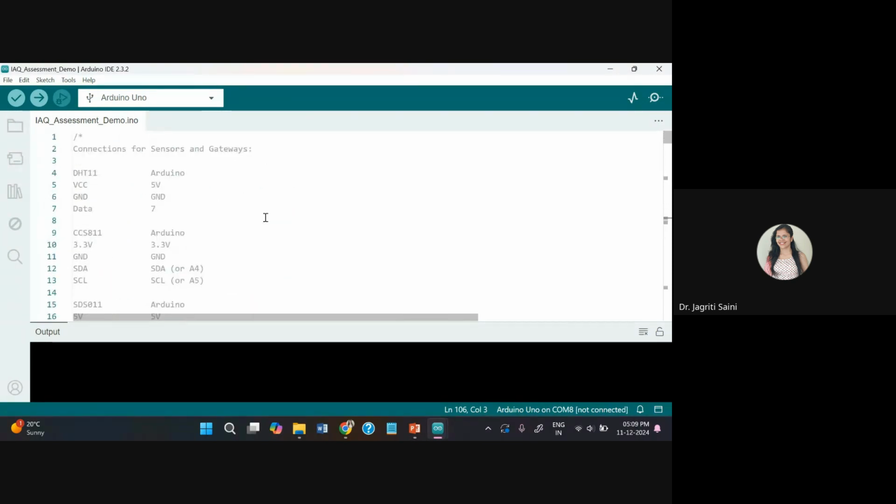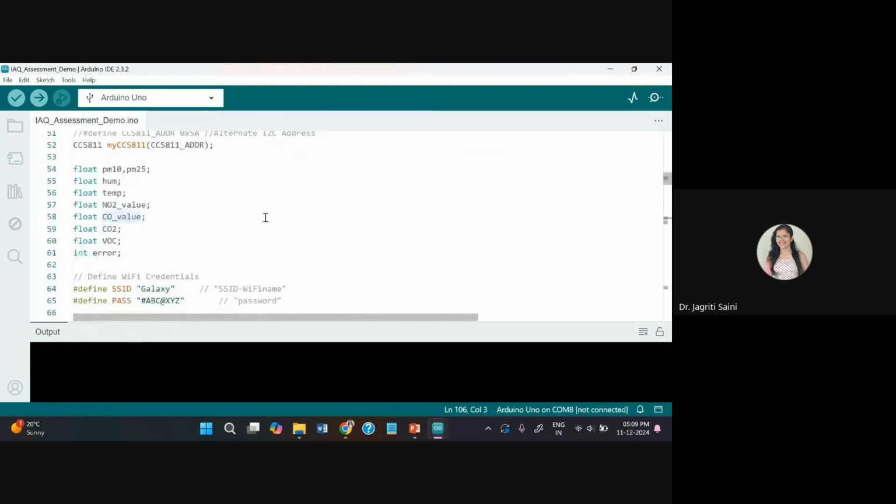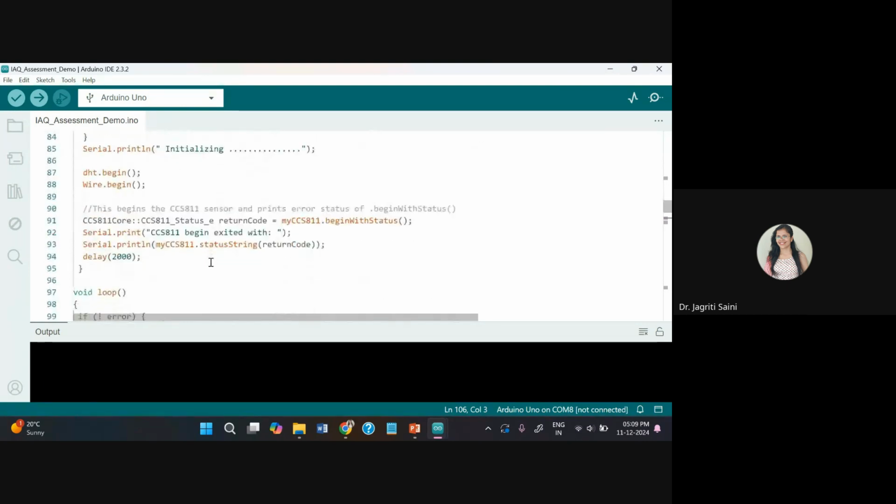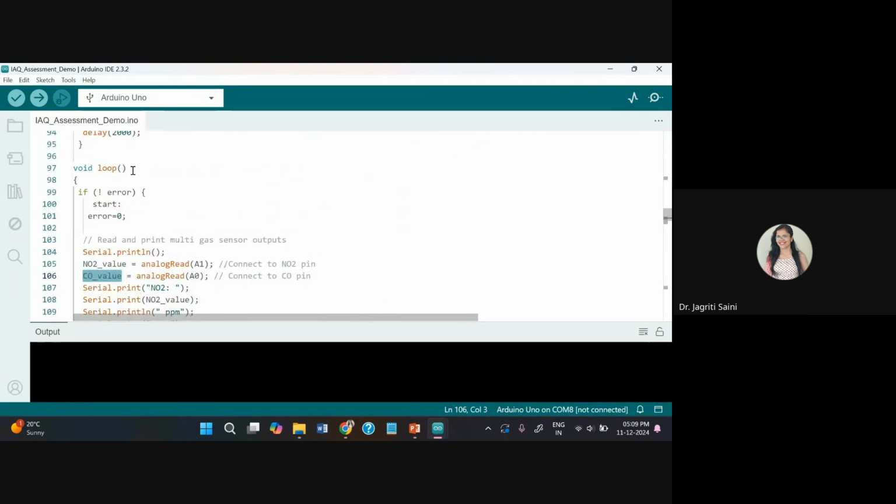Remember that whenever we declare variables before the setup section like here, they are called global variables, and the values stored in them can be used throughout the program. If you declare any variable within any specific loop section or any specific area that is used in a small subroutine, then it becomes a local variable and you cannot access that variable outside that section.